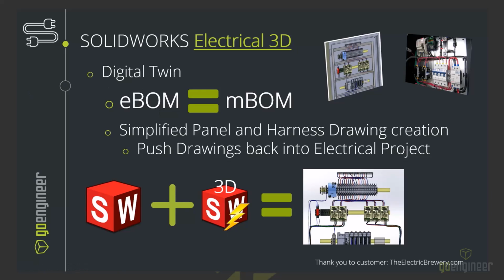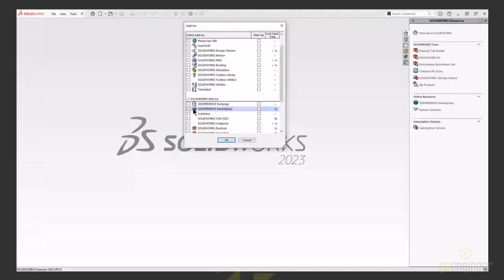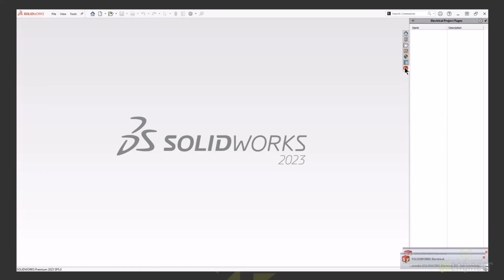Okay, so let's dive in and take a look at Electrical 3D here. So this is SOLIDWORKS CAD, so a different product. So the schematic software can run on a machine that doesn't have SOLIDWORKS CAD on there. So you don't have to have schematics on a machine running Electrical 3D, but you do need it somewhere in the building, because that schematic needs to be created. As far as the add-in goes, again, because it's a separate license, you come into the add-ins, you turn that on. Okay? So I've launched SOLIDWORKS CAD. I'm turning on the Electrical 3D license there. And here in just a moment, we'll get an extra little tab that shows up right there, letting us know that it's ready to go.